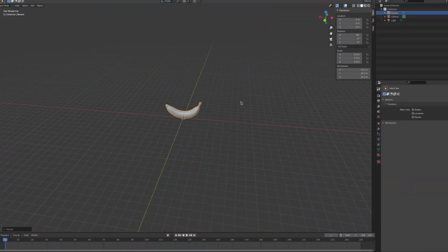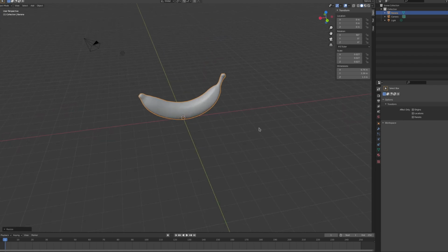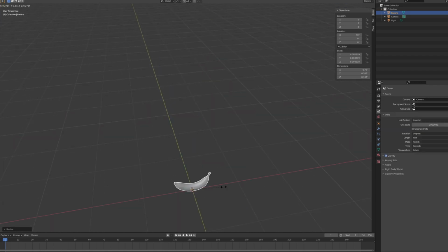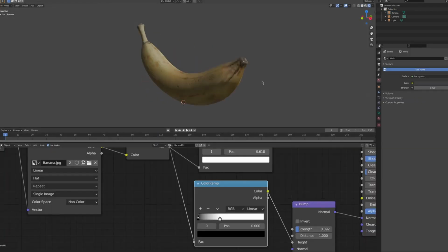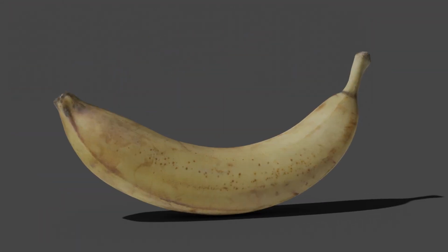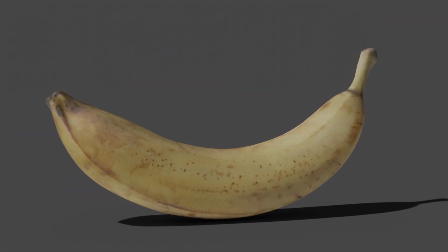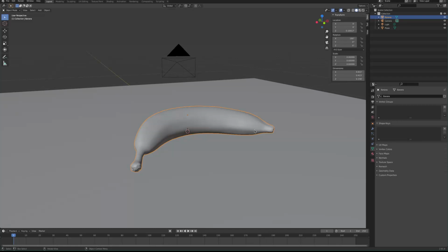If we're going to cut this, we need some extra models to split it into, because like most 3D trickery, we aren't simulating an actual cut, just using some smoke and mirrors to look like we're cutting this thing in half. To get a clean cut, I'd recommend using booleans. There are other ways to cleanly split a mesh, but I find that booleans are pretty quick, pretty easy, and since they were improved in Blender 2.91, they're pretty stable too.